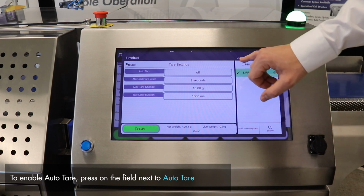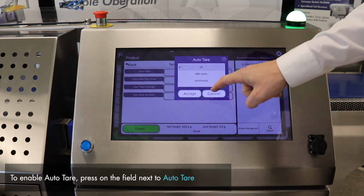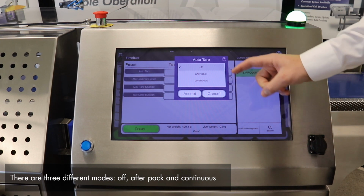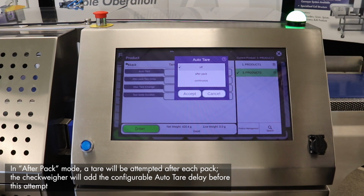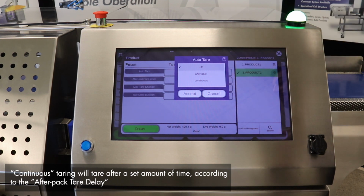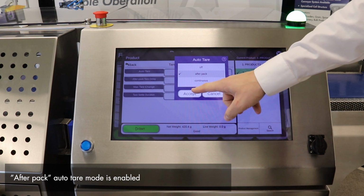You will note that currently auto tear for this product setting is turned off. So we're going to go in and enable auto tear. Within this menu, we have three different modes. We have off, after pack, and continuous. After pack tear mode will attempt a tear after every pack has left the weigh conveyor after a predetermined delay. Continuous tearing will tear after a set amount of time that is set within the next menu. We're going to enable the after pack auto tear on the system.